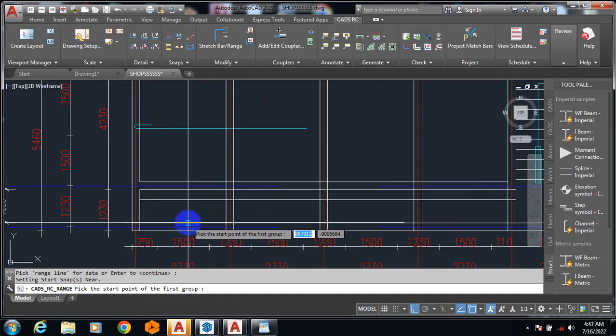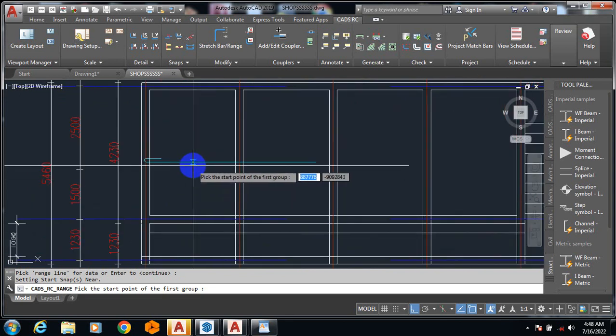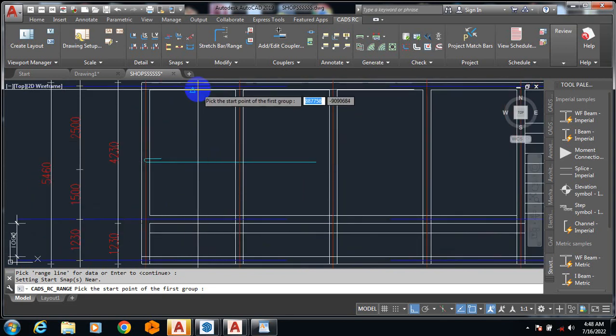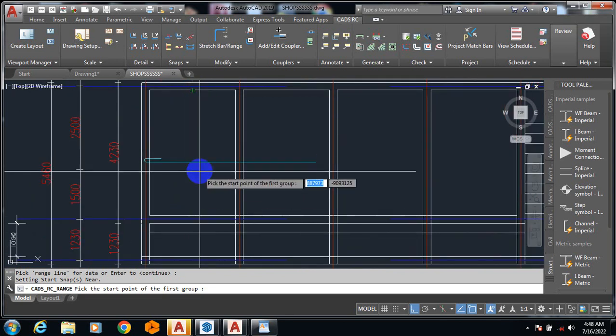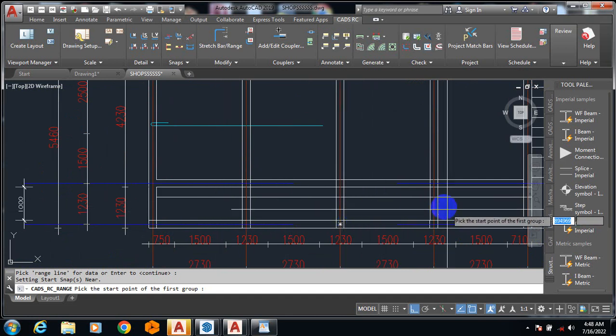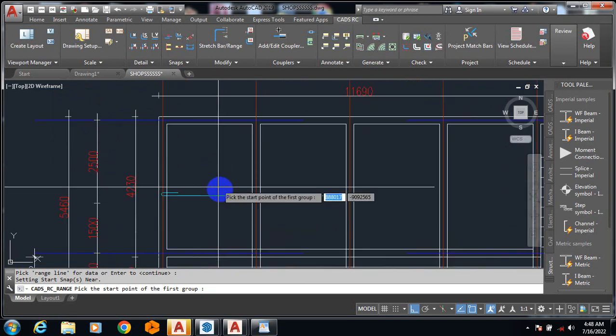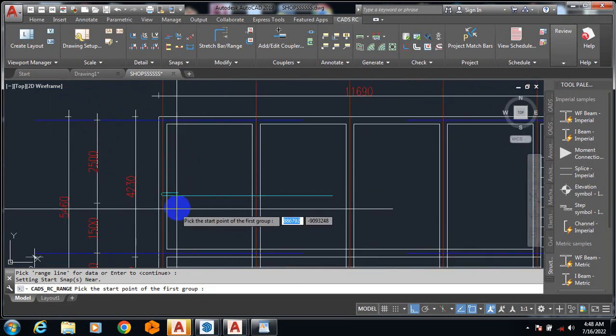or I can make this span, all right, let me just do something quickly. So if this spans from here to here, because this panel is actually a one-way slab, but this is actually a two-way slab. By the time you do your ly over lx, I believe you understand that.